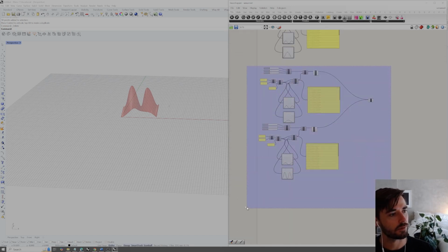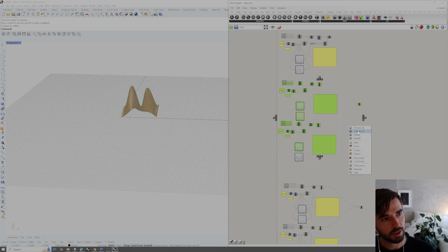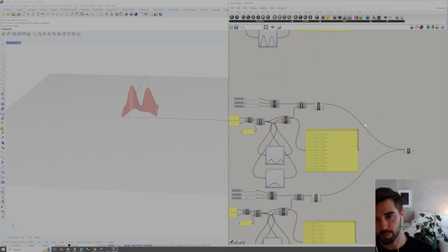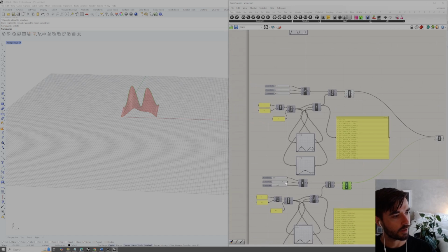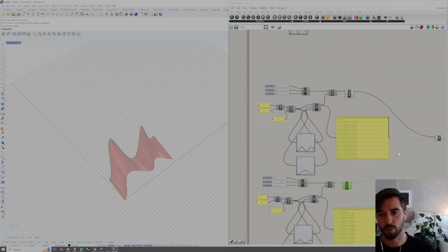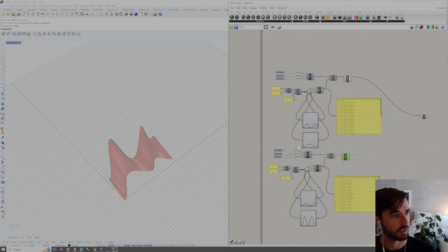If we select all of these, copy them down, just like we did in Rhino, after Loft, we went through Sweep, which took in, at least for Sweep 1, 1 rail profile and then 1 sectional profile. So we have 2 curves here, but right now they're not starting at the same origin, which for Sweep is not going to create a clean sweep.